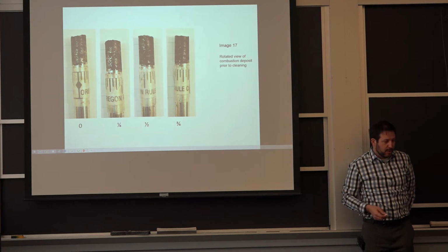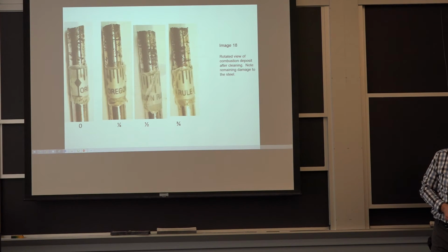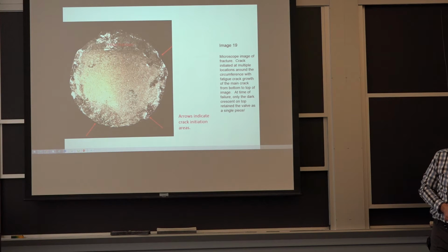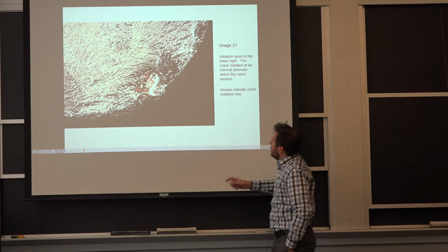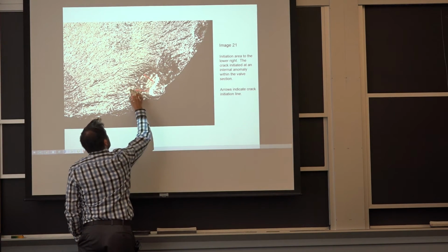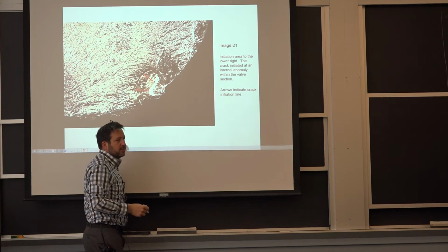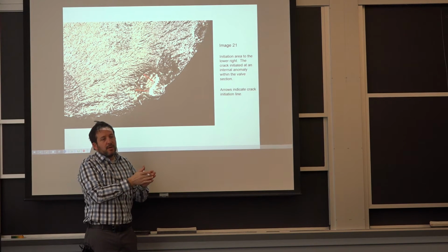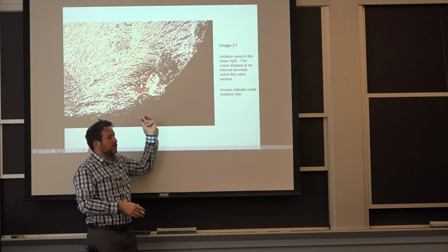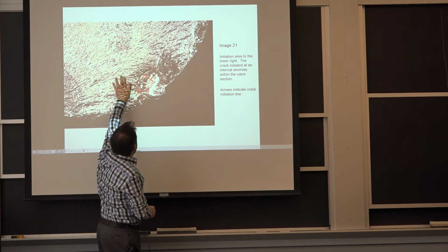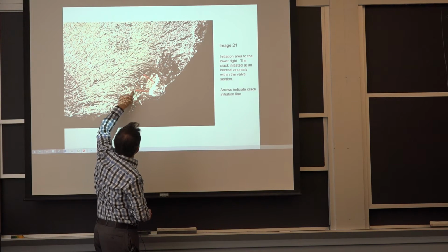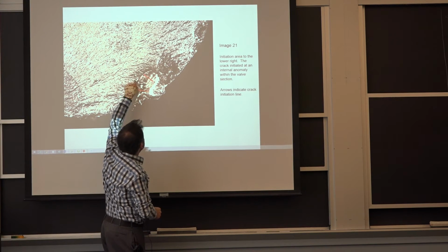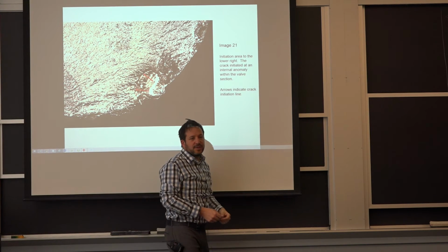Essentially the fracture surfaces are giving us that information very clearly: you had a hole and then you started some cracks after the hole was formed, because you have all these small initiation sites around the hole. If this crack started here, it wouldn't be giving me all these initiation sites. It wouldn't give me 20 initiation sites all around it.